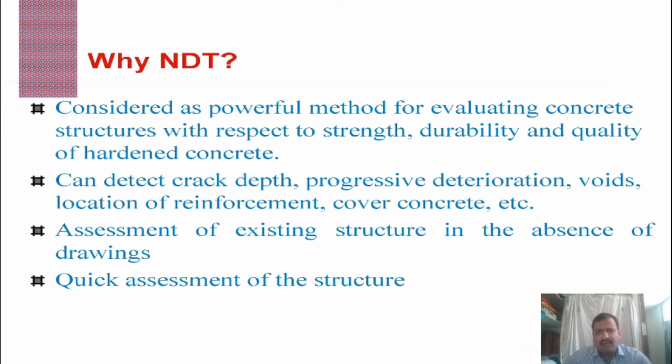So why do we adopt NDT? Non-destructive techniques are considered a powerful method for evaluating concrete structures with respect to strength, durability, and quality of hardened concrete. By using this method, we can detect crack depth, progressive deterioration, voids, location of reinforcement, cover concrete, etc. Assessment of an existing structure in the absence of drawings can also be achieved, and by using this technique, quick assessment of the structure can be achieved.